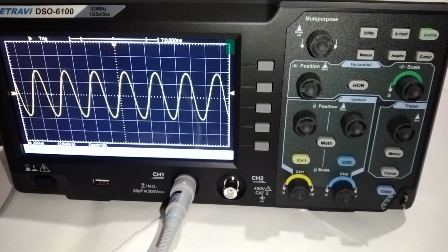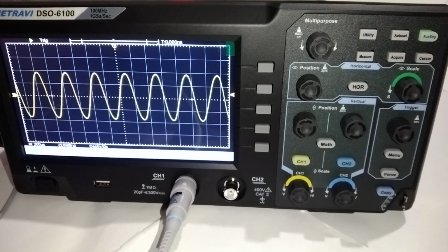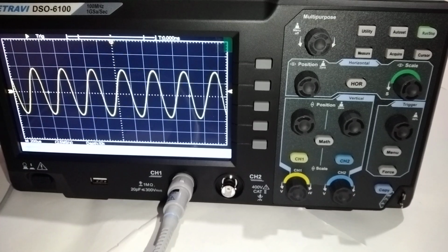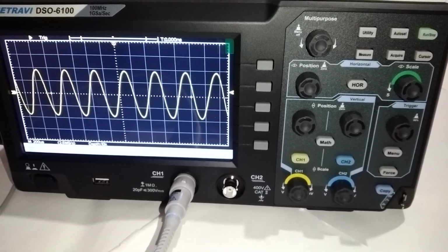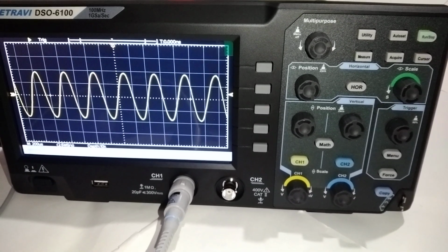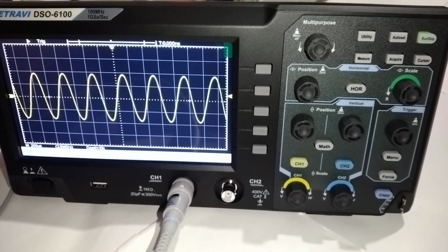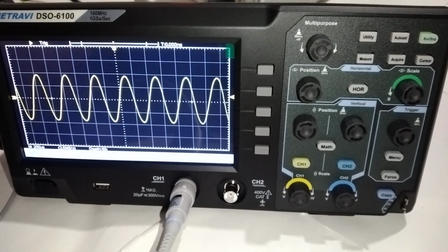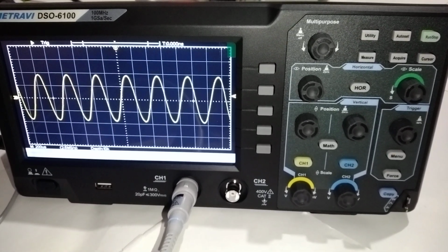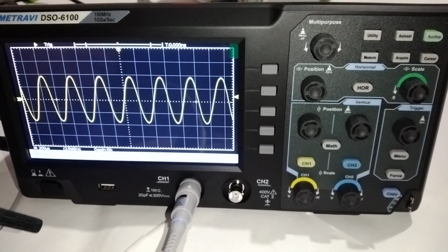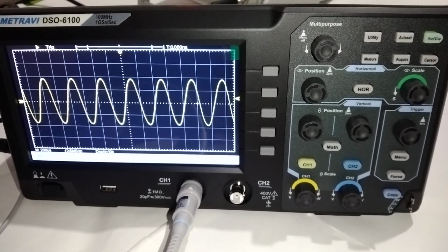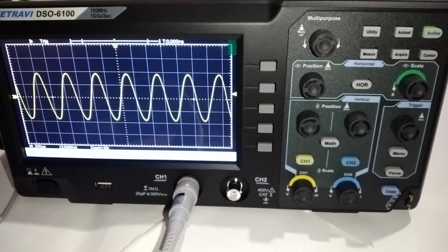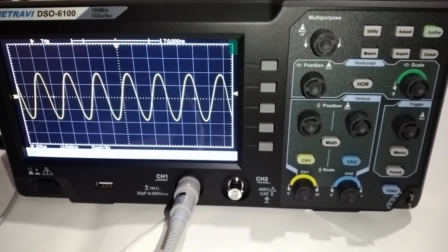This is very important to note, because you should not assume that these are electrically isolated. Electrically isolated means it can be isolated using an optocoupler or another way, by separating ground or any other way, but these are not electrically isolated. Hence you should be very careful when using two channels to see the results of the instrument under test or device under test. So this is a very important point.